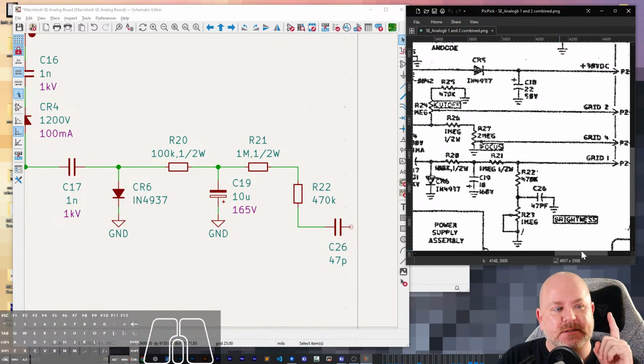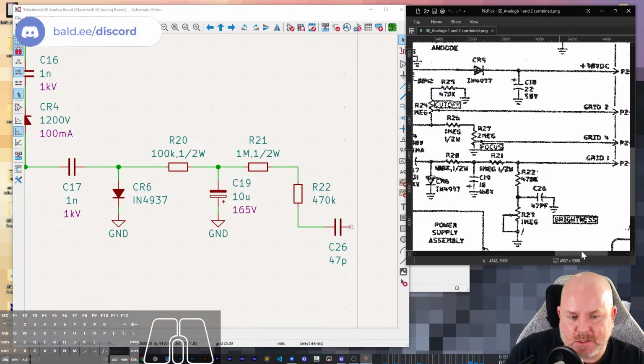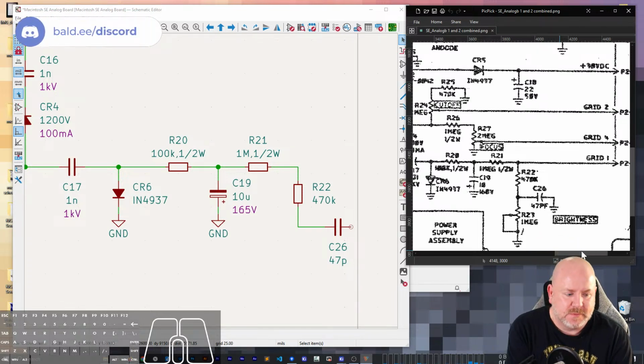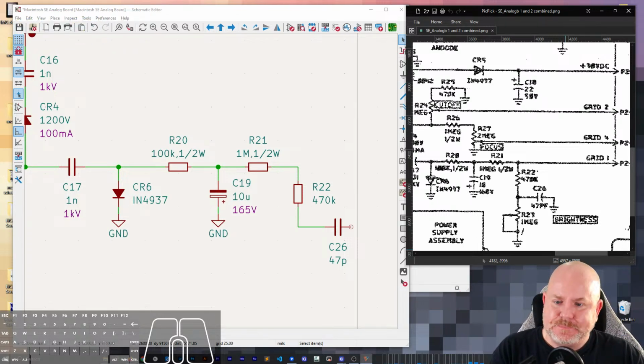The only thing I would say is that if you're using a hot plate or a reflow oven with bismuth, you really need to soak for a couple of minutes around 100 degrees C, maybe a maximum of 120, because you have to give the flux time to activate. Since reflow happens at such a low temperature, the flux in the paste doesn't necessarily have enough time to activate. So you want a soaking stage to give the flux time to do its thing. But once you learn how it works, I prefer it. I'm all about it.